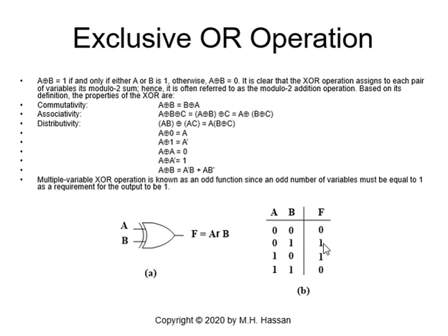Okay? In the second row, when F is 1, A is 0 and B is 1. So we say the complement of A, which is A prime, because A is 0, which indicates A prime, then B because B is 1. Here, this is actually called the minterm. It is A prime B. We will cover this later on in more depth. So A is 1 and B is 0, so it is A B prime.